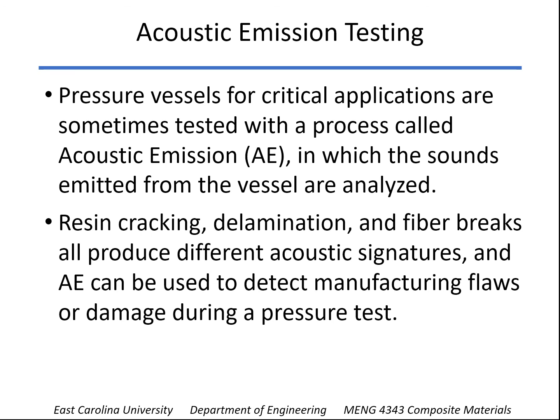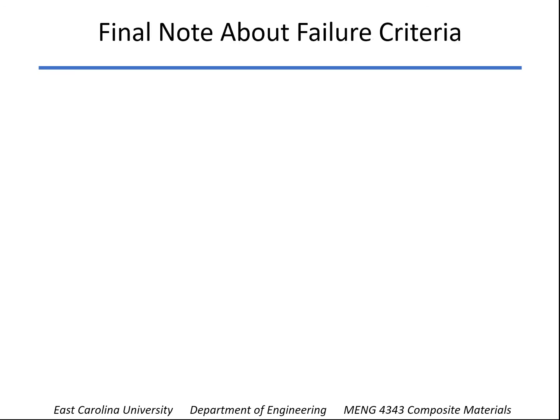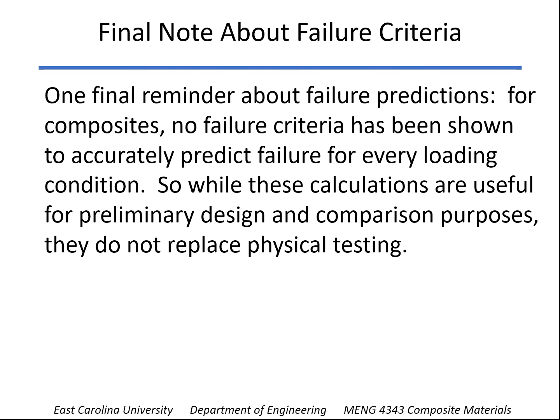Okay, so one last comment about failure criteria that we mentioned at the very beginning is that there is not a failure criteria out there that's been shown to accurately predict failure for all materials in every loading condition. It's still very useful to know this for doing preliminary design, for comparing designs, but always keep in mind that certainly if this is a critical application, you have to do physical testing to confirm those calculations.